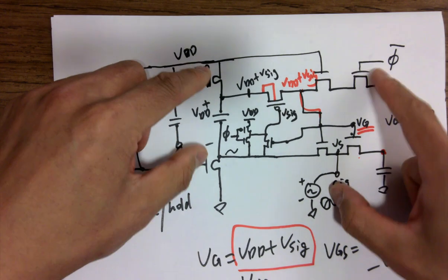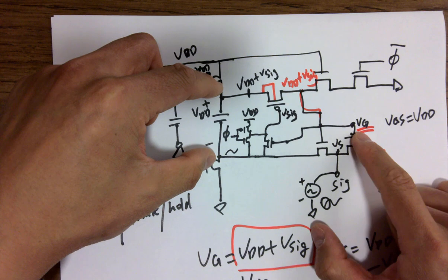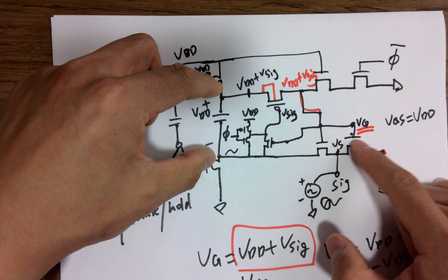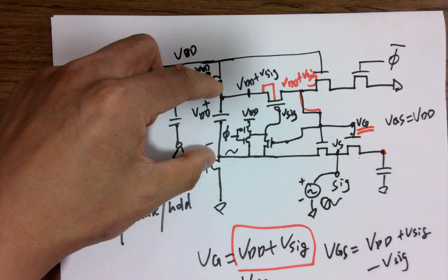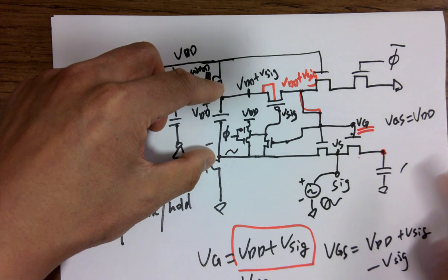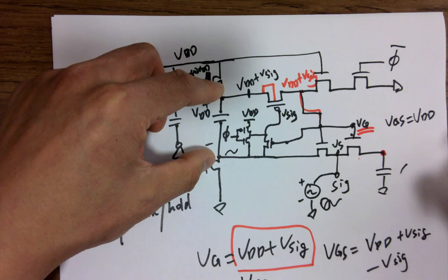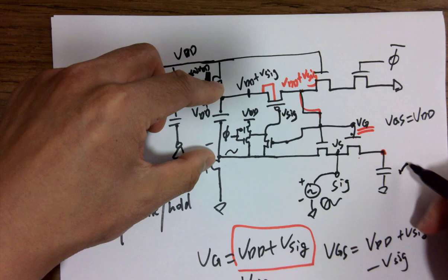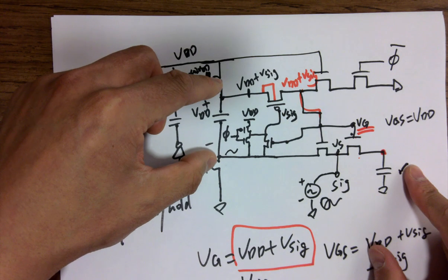Whenever there's 0, there's a VDD over here, and then this starts going up as well because this is on, and there's no distortion because it's a constant VDD, and this will pass and charge up. So you will see a little bit of delay, but it's not getting distorted. The capacitor is sampling starting from here and then tracking whatever the signal is doing, still going up.